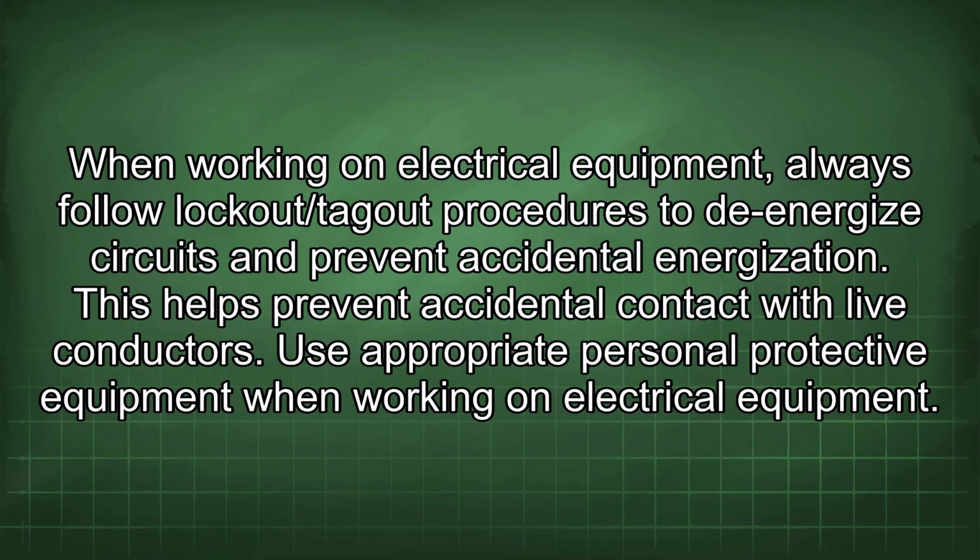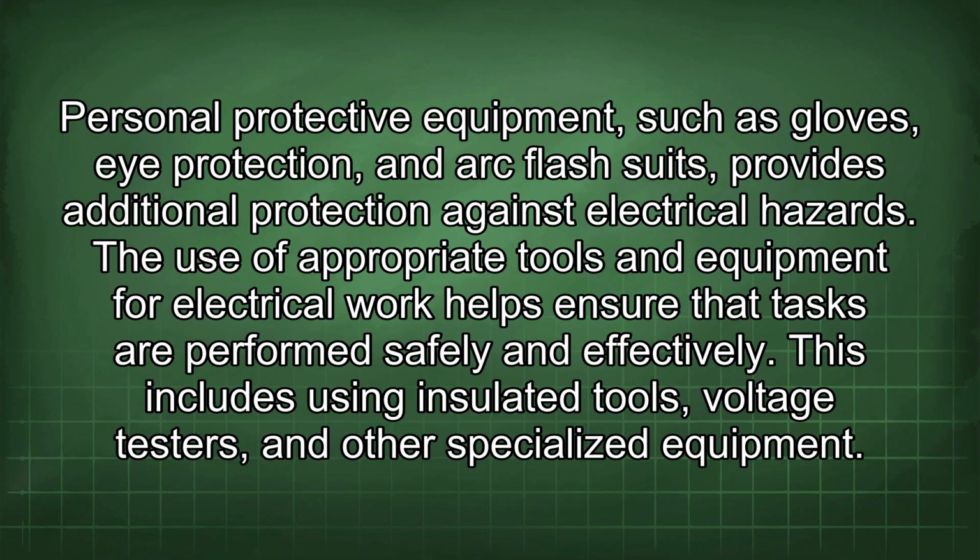Use appropriate personal protective equipment when working on electrical equipment. Personal protective equipment, such as gloves, eye protection, and arc flash suits, provides additional protection against electrical hazards. The use of appropriate tools and equipment for electrical work helps ensure that tasks are performed safely and effectively. This includes using insulated tools, voltage testers, and other specialized equipment.